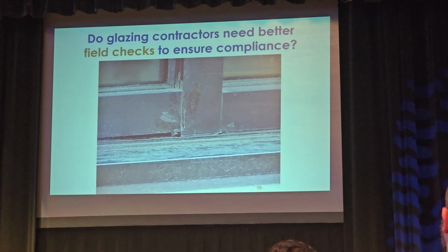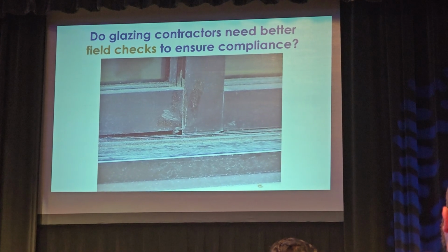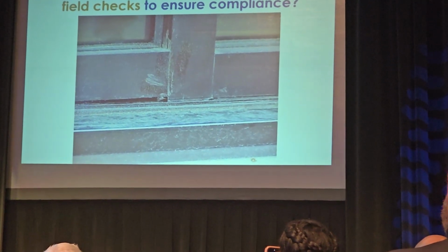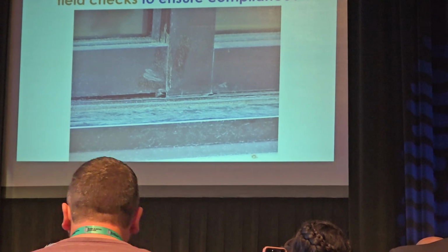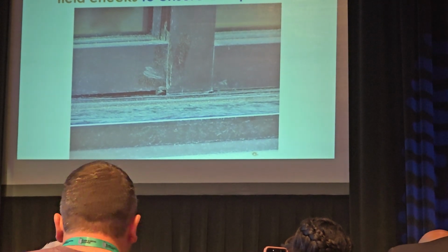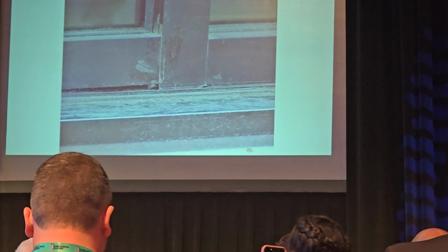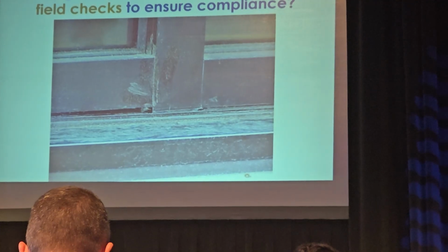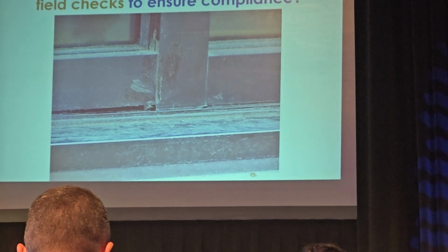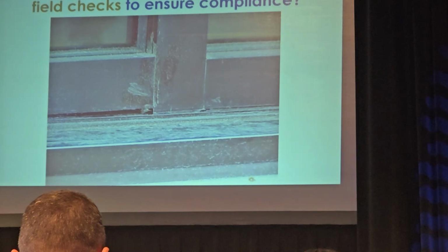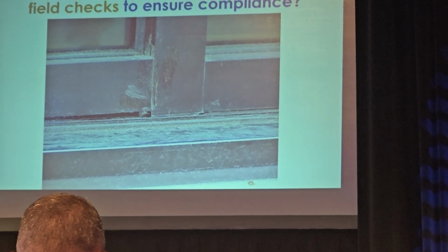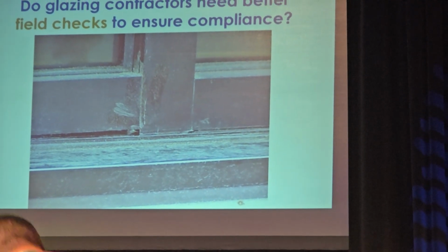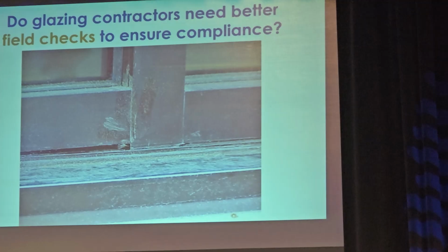Yeah, anything, like look at this picture right here, anything between a curtain wall and a storefront, whether it's a shear block insulation or screw spline insulation, that there is just poor fabrication. Aesthetically, whether it's on the third, fourth, fifth floor or on the first floor, some untrained professionals out there might try to just put ceiling over top of that. That's not the case. We're trying to train everybody to do things properly before you even get to that situation, let alone the aesthetics of the step between both horizontals on each side of the work too. This is just something that's a failure, aesthetically and for thermal and sealing, for water penetration.